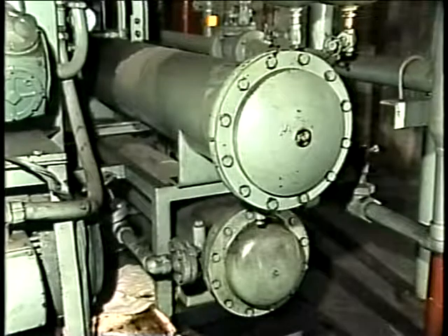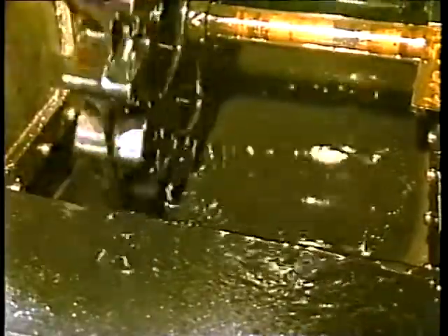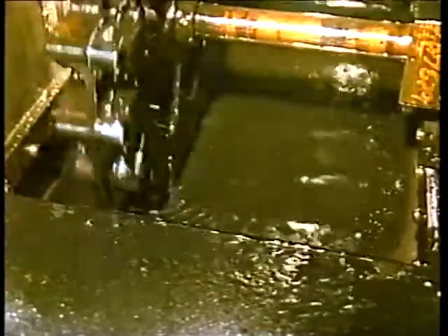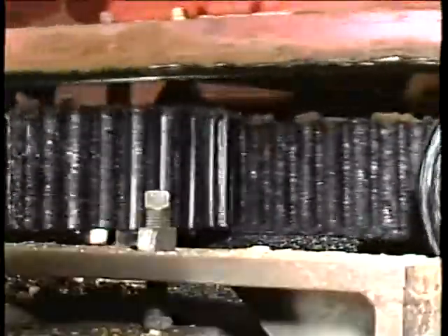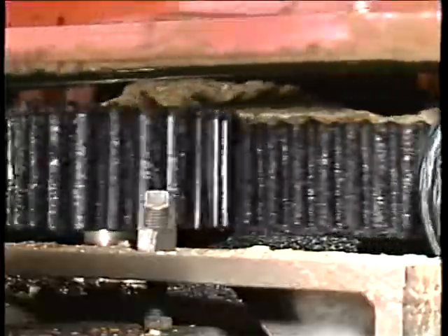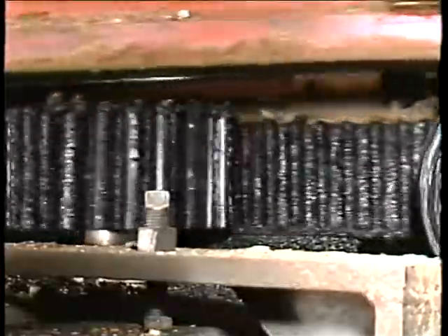Overheating could be caused by a loss of cooling water flow to an oil cooler. Temperature may also become a problem if it's too low. If the temperature is too low, lubricant flow may become restricted, which robs the gearbox of its lubrication. Another lubricant condition that can cause gear problems occurs when lubricants become contaminated with dirt, sand, metal particles, sludge, or acids.